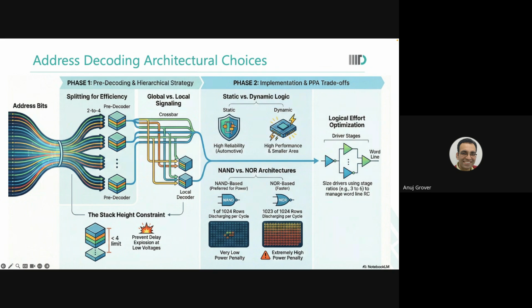Are you with me? So there is no single formula that these particular bits must be used for the page. Based on how you use them, the scrambling will change. Now you like that scrambling, you do not like that scrambling, that is your choice. You have an agenda, you want all the adjacent words to be on the same page, you would use LSBs on column decoding.